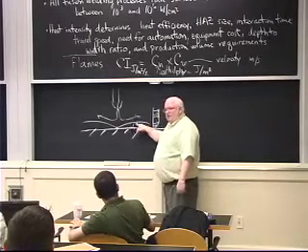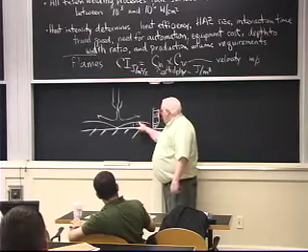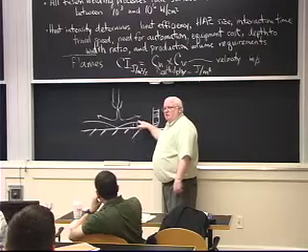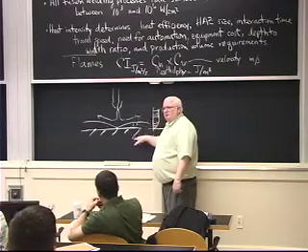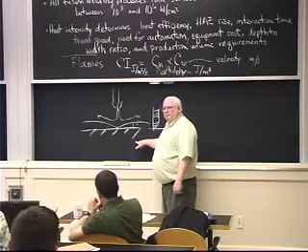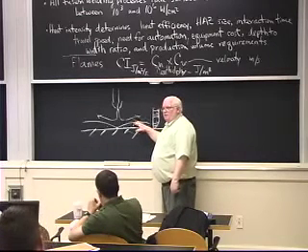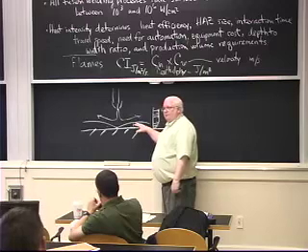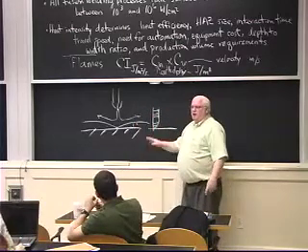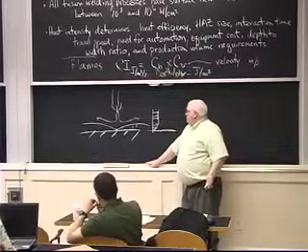And this becomes sort of an insulating layer of air. The heat transfer across that boundary layer limits the heat conduction from the hot gas to the condensed phase, solid or liquid, whatever it is. So I'm boundary layer limited in flames, except in 2 cases, which we'll talk about. Tricks of getting around the boundary layer that we use in different things.